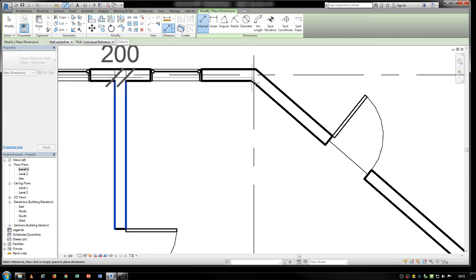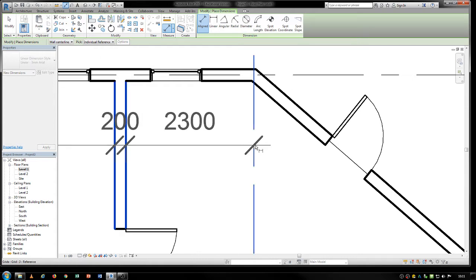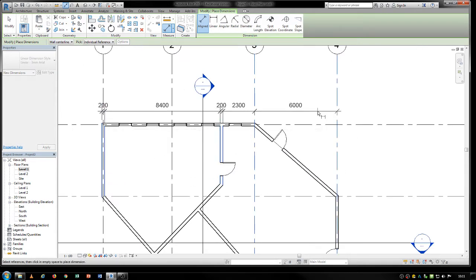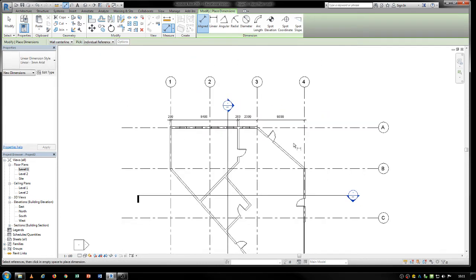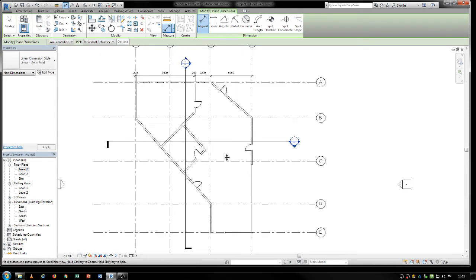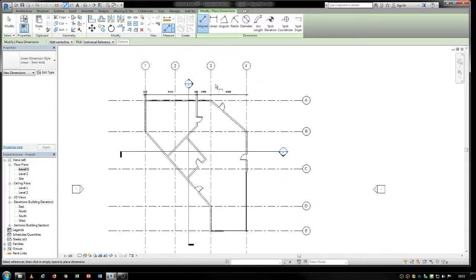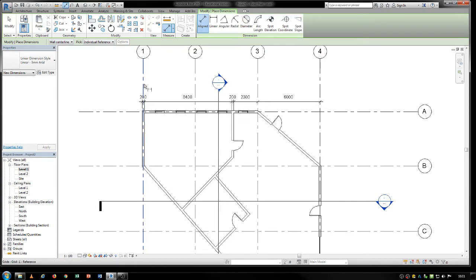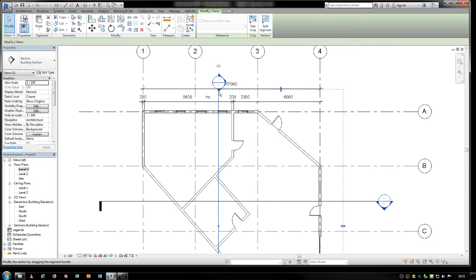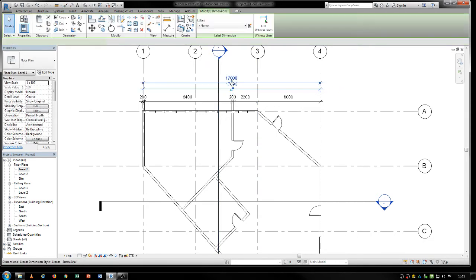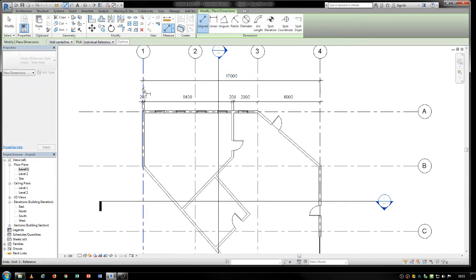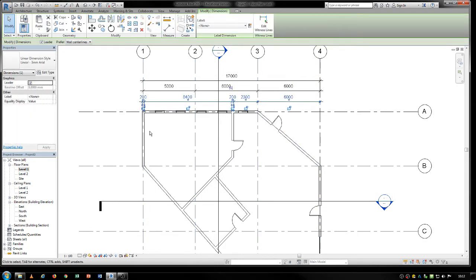So probably it's best to measure it somewhere to that grid, and then go to the next grid and then put it here. So usually the way dimensioning works best, I don't know what Branko and Matt have shown, but usually you have a series of lines from outside to inside. You will have the biggest dimensions here, so that's maybe the overall. I'll just move my section line away so that's not distracting. So usually you have the biggest line here, then you would do probably the grids, then you would do another line that is addressing some of the walls.